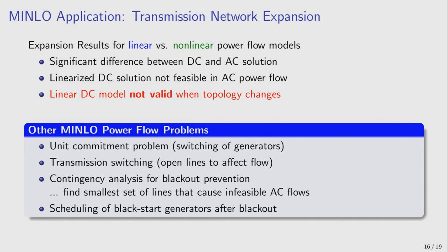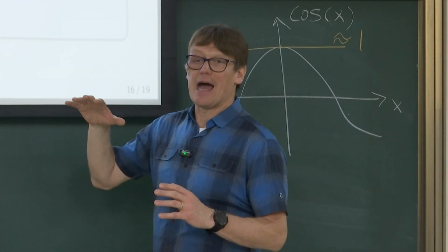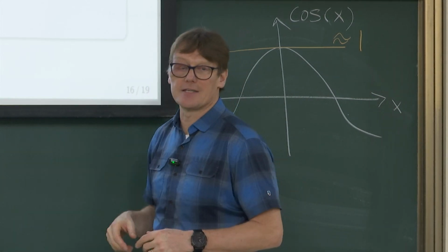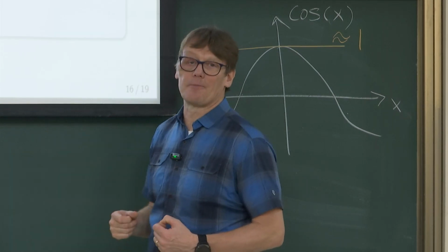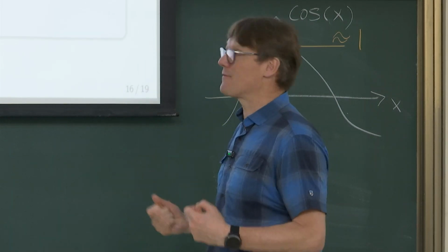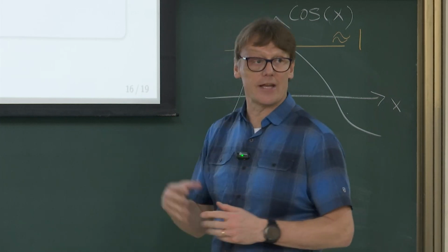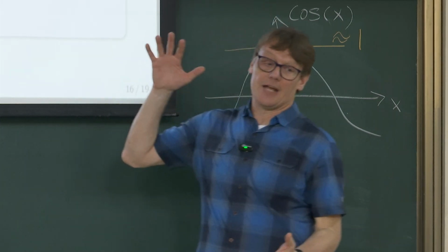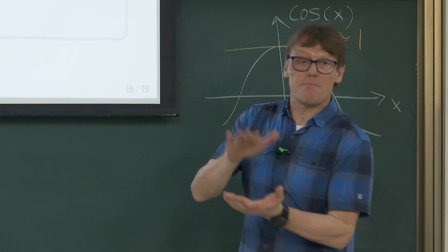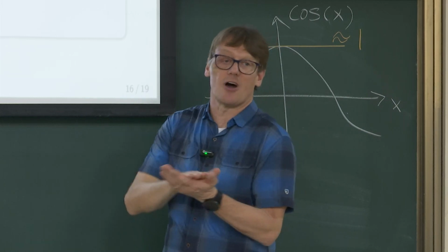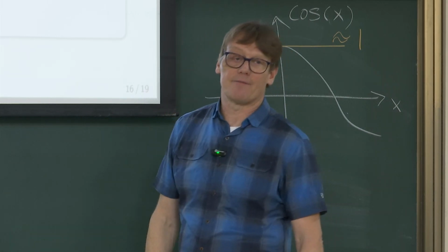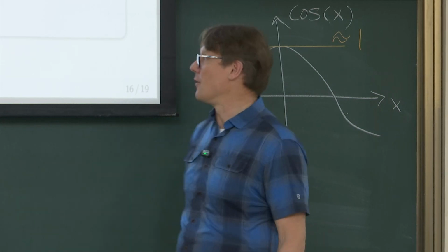You want to do that because by switching lines on and off, you can influence how the power distributes through the network. And so you can manipulate the power flow in the network, and you can do that sometimes to safeguard against some things. For example, if we have geomagnetic induced currents, and we know which way the magnetic field is organized, we may want to switch some of the lines off that go through these magnetic fields in a certain way so that they don't overload.